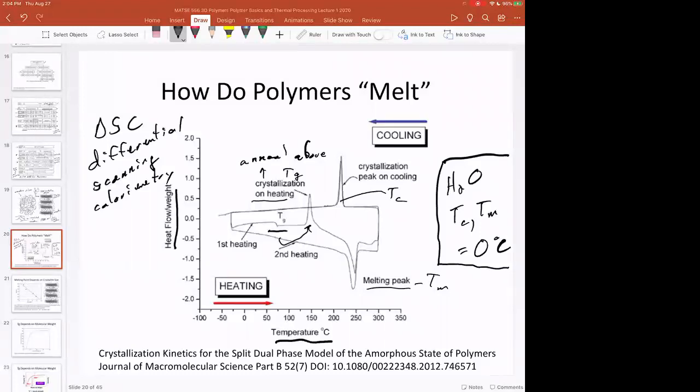And there's lots of cool stuff that you can do. Like you can strengthen materials by annealing them above TG, just like you can increase the grain size, or change the grain size, in metals or ceramics or something else. So there's a lot of things wrapped up in here, but looking at these differential scanning calorimetry data and connecting it to your additive process tells you a lot about what's going on, assuming that you're processing a thermoplastic. And we'll look at DSCs of thermosets as well, because that tells you other things that you need to know, like curing temperatures rather than thermal transitions.